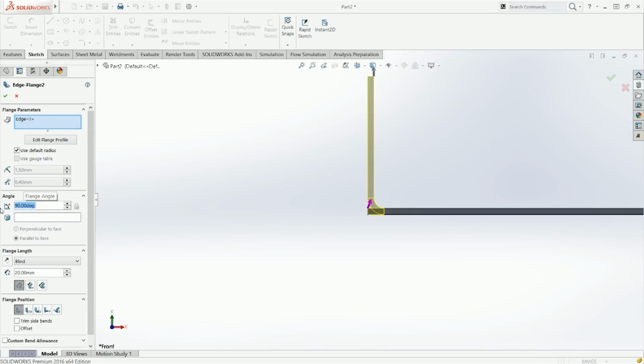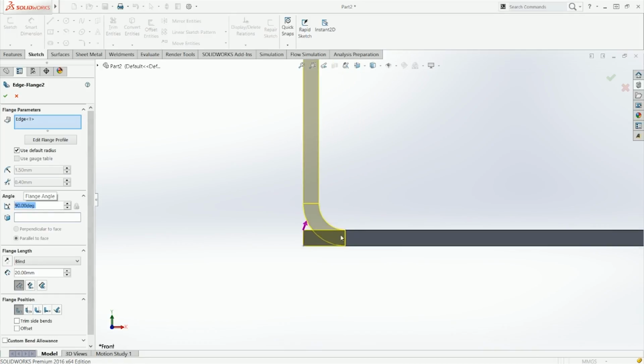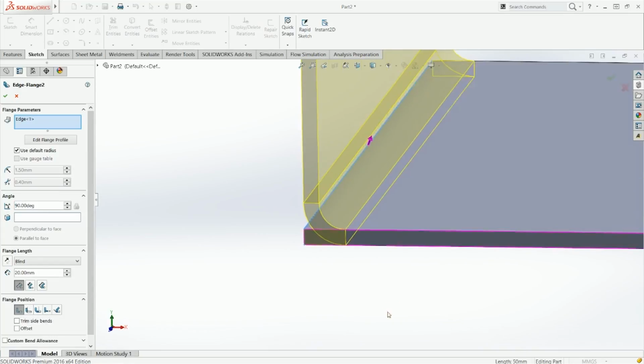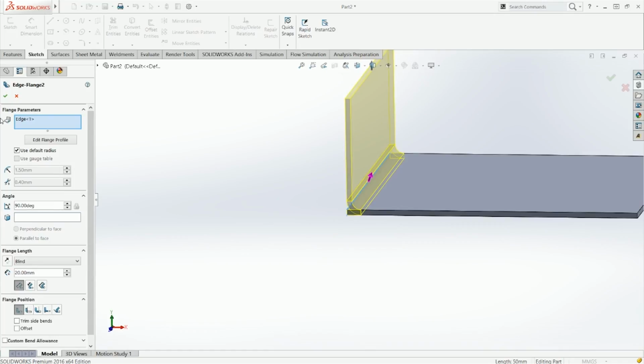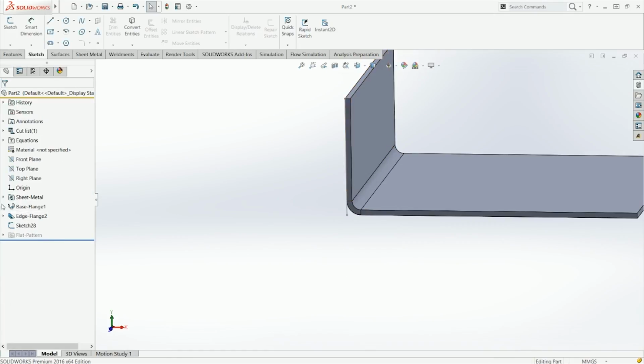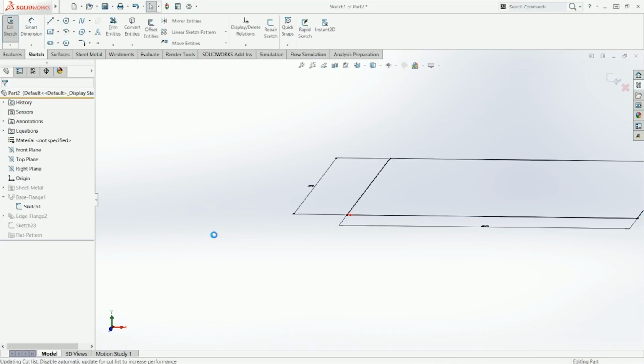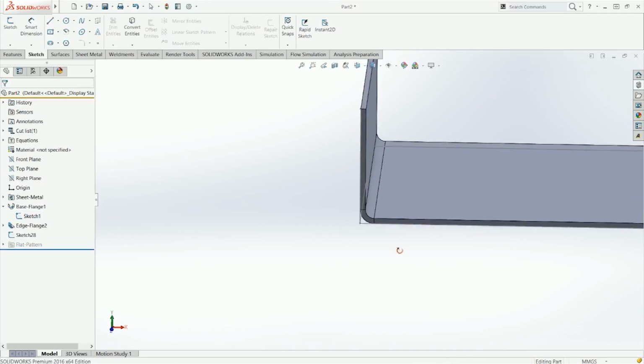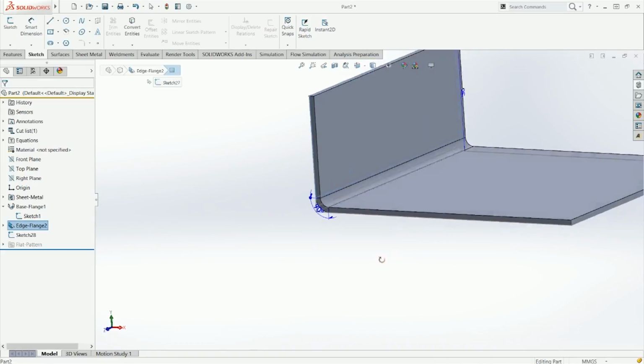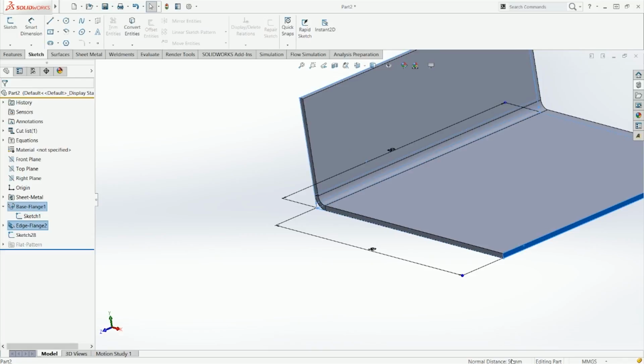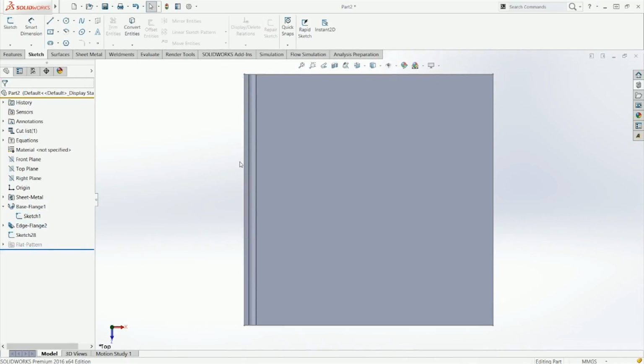So I'm going to go back to 90 here. Keep it like that because I like the point where it starts. And here you can change the flange position. The flange position is basically where this line starts. So as you see, we defined our square as 50 by 50. And if I show it, it's not edited, show it, there you go. If I measure from there to there, it's going to be 50 mils. And as you see, it's inside our defined square.